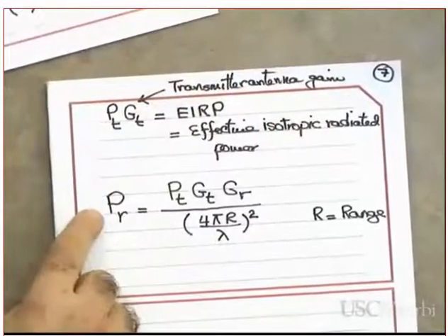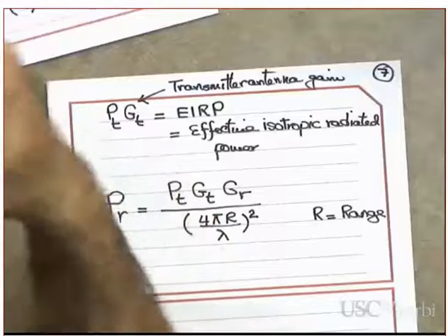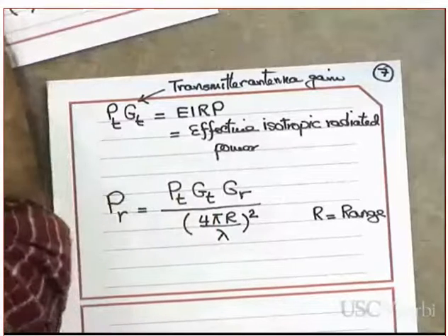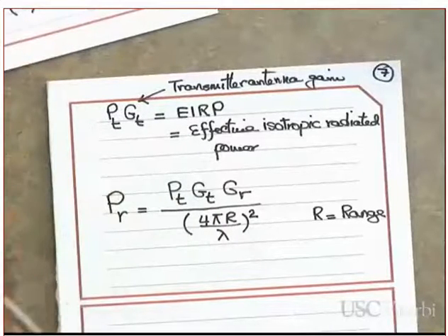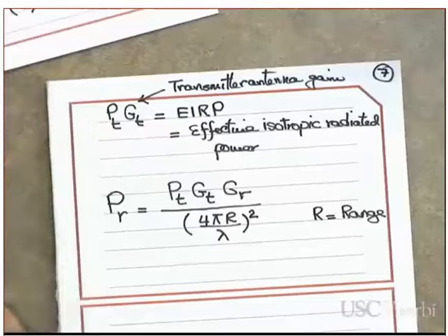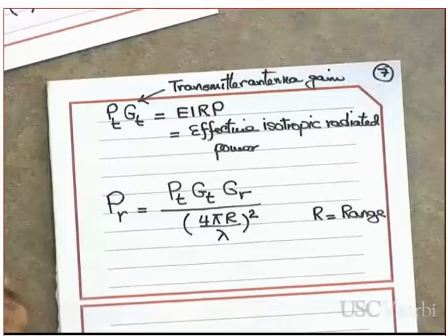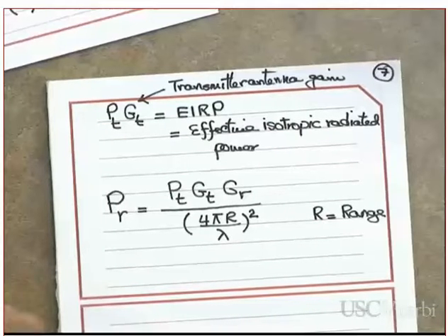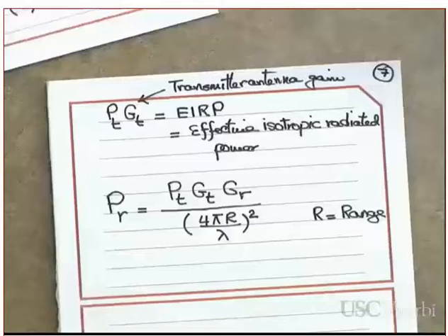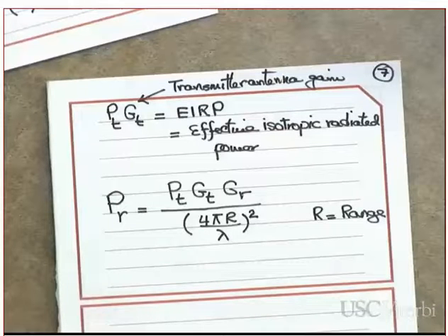To get the same received power using free space, the range needs to be reduced. Did you understand that or not? Yes. And that is one of the reasons why they make the cells in downtown LA or in a dense urban environment smaller and smaller. Yes or no? Because there are a lot of obstacles and the multipath is so bad. Yes or no?